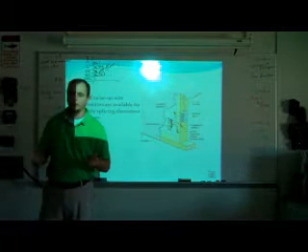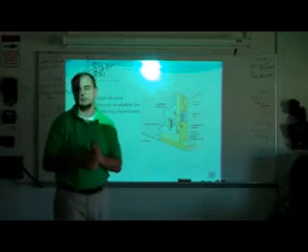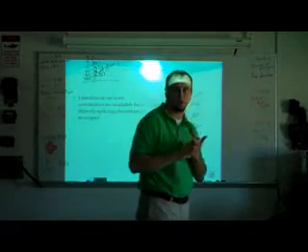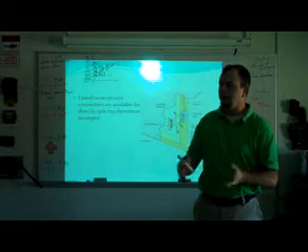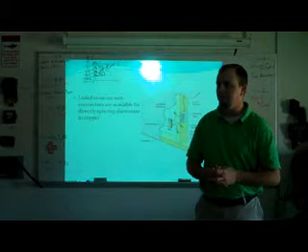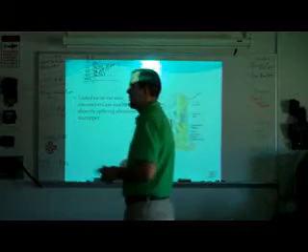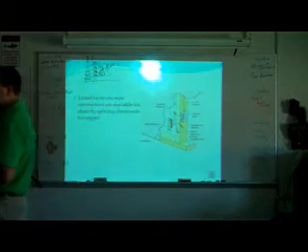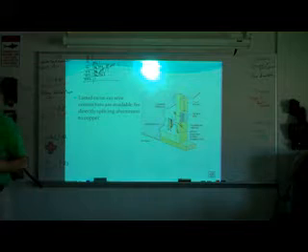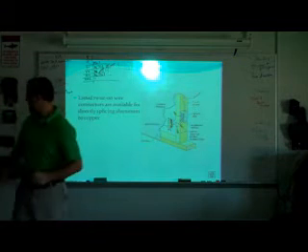What's another name for oxide? Rust. They will actually corrode together. And what's that corrosion do? It increases resistance, which increases my heat. If I increase my heat, what's that do to my conductor ampacity? It lowers it. That's how this guy burned up.